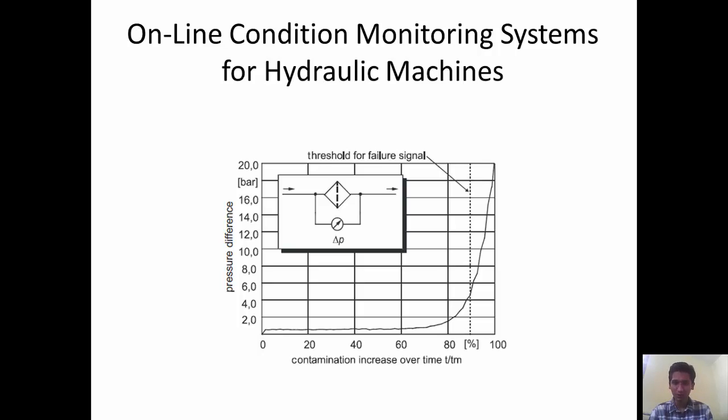Here, between these, the filter is there. As seen in the diagram, when the oil passes through the filter, the filter filters the oil, and it also shows how much pressure is involved. If the pressure goes above 3 bar or 4 bar, the oil will pass through the bypass to the output.